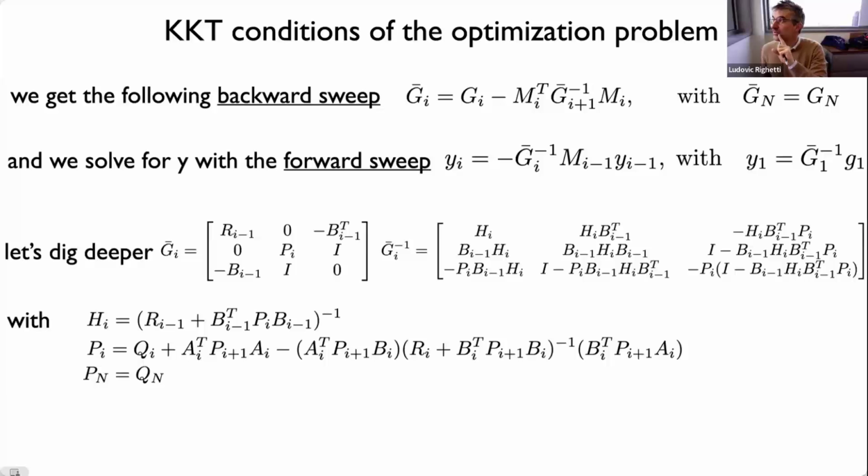I don't want to say something wrong. I have to write it down because I don't remember. But normally you're going to double the number of states, the size of your matrices at least. So basically you're going to lose a factor 8 in the complexity of the inversion of every matrix. And that's what you see. Some people have implemented this kind of augmented Lagrangian DDP style thing, and they have a factor 8 that they cannot get rid of because of that.